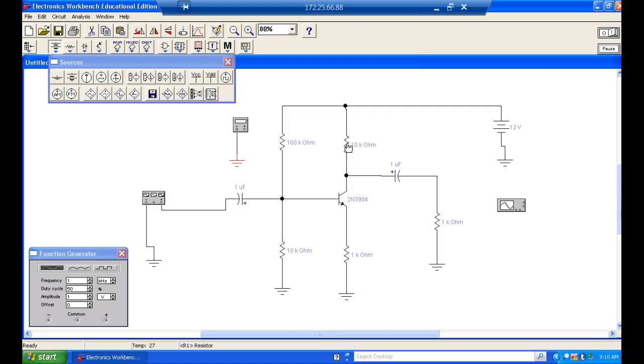So that means to get 600 micro on my 1K, it would need to drop what? Instead of 400 millivolts, it would need to drop 600 millivolts. Okay, 600 millivolts. So that means what would I need on the base? So I'm going to take 0.7, add 0.6 volts to it, right? What would that give me? 1.3 volts, right? So we need this guy right here to drop 2.3 volts.